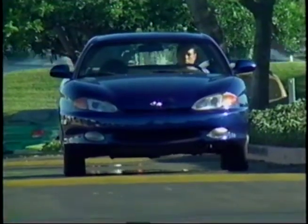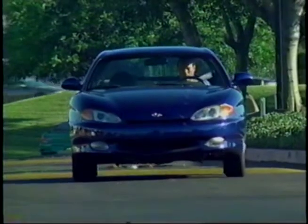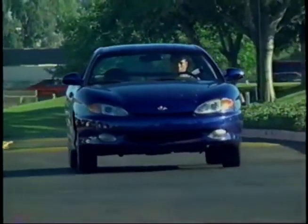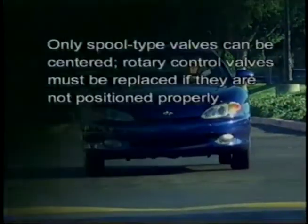Power steering gears have one more adjustment. The control valve must be centered. If the valve is not centered, the car may drift or pull or have poor steering wheel return in one direction. Only spool-type valves can be centered. Rotary control valves must be replaced if they are not positioned properly.